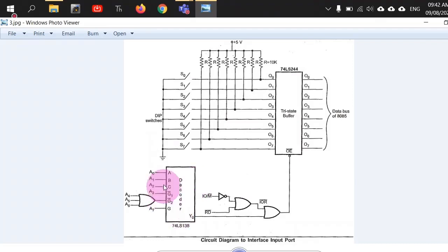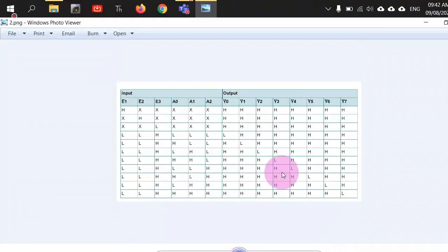So for this particular case, when we had 80, only this G signal should be activated and rest everything should be deactivated. But now if you want to attach it at 55 location, so you have to have a 1 here, so you will be applying a NOT gate here because this is configured for 80. So ultimately that 55 should be converted to 80 first for attaching it here, so that only G is activated. So you have to use appropriate NOT gates if any input happens to be 1 here, right? Because this is now configured for 80 only. Or otherwise you have to go to the truth table and see for which combination you are getting this 55 here, and accordingly the hardware should be interfaced.